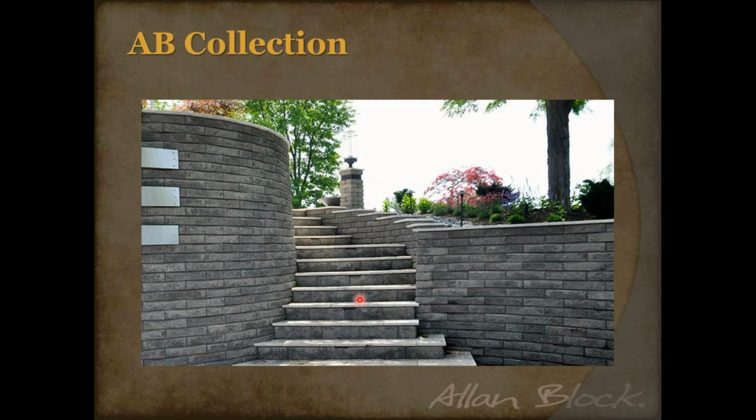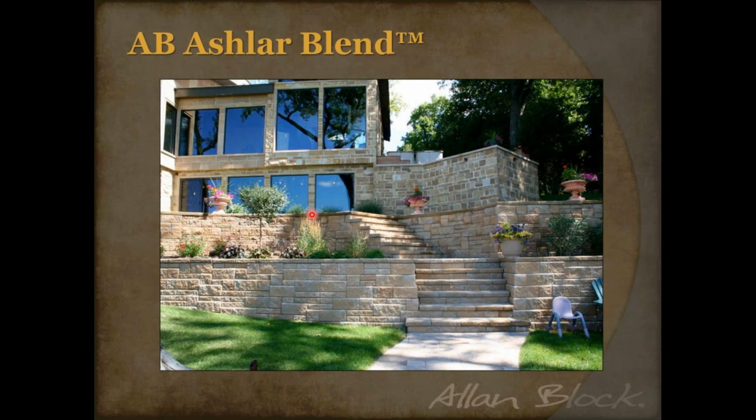Here's another application where this was an award winner for the Hardscape North America set of steps where they did tiles, kind of blended it out, entryway into here, and then they used the setback and hid the setback by curving the steps around the wall itself, because that's important. We want to try to make them look as natural as possible, whether it's an ashlar pattern or a regular pattern. But whenever you do your stairs, just use the full-size blocks. Make it as easy as possible.